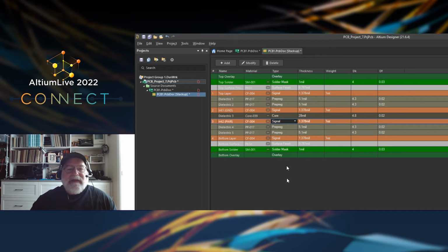I've got my stackup. And we'll adjust the dimensions of the prepreg layers or the core layers. We've got different thicknesses, and different thicknesses for the copper. So here is 1 ounce copper. We can change that, of course. We could do ½ ounce copper, and there's the new thickness. Let's make this ½ ounce in the middle, and let's go back to 1 ounce up above. And there are the dimensions.